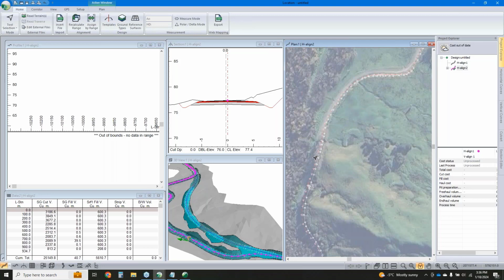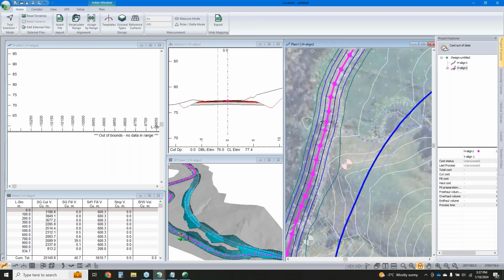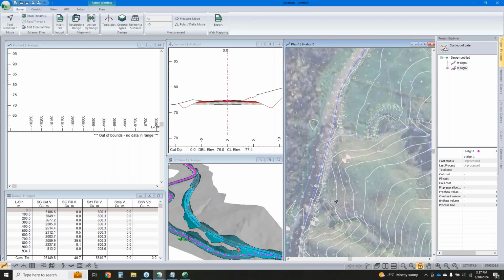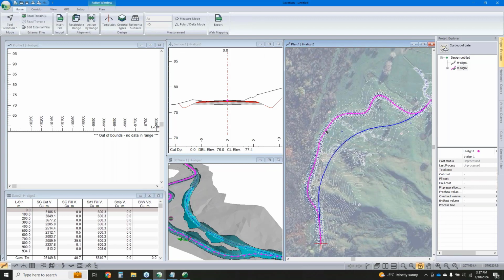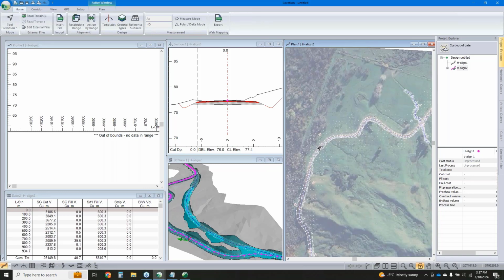So we've got that, and right now, if we leave that as is, every surveyed point along that line is an IP. So the standard way to go about that would be either, well, trace it out and simplify it into just curves and tangents, or delete sections where you wanted to leave them as tangents and isolate it out.